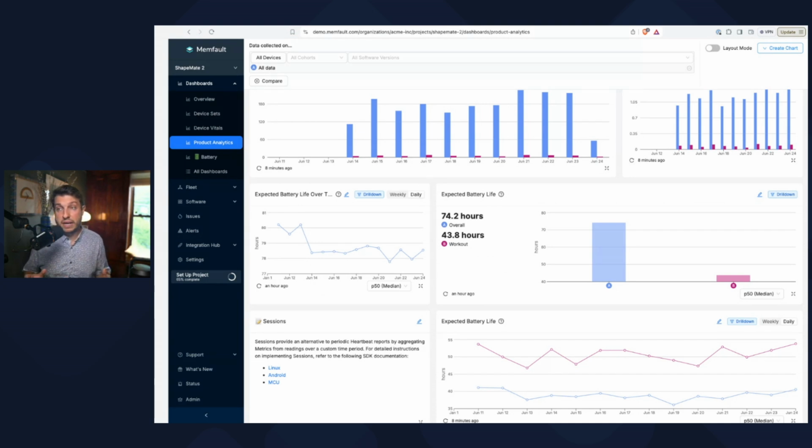I think that can be expected, right? Voice commands require sending more data over BLE. It requires having the mic be on, probably writing more data to flash. There's going to be a trade-off, but now we know that in real world usage, that trade-off is 2 hours. Likely is okay, though we'll look at the distribution to see if there is something that we need to investigate later.